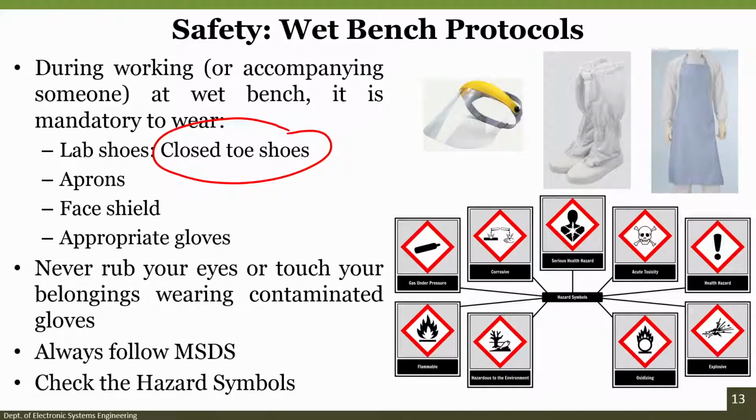So, you need to also follow the MSDS guidelines. You have to check the hazardous symbols when working in the clean room. As you can see here, there are a lot of symbols, for example, gas under pressure, corrosive, then serious health hazards. Even breathing these chemicals will cause a serious health hazard, like breathing VOCs, which are volatile organic compounds, will cause serious lung damage. Acute toxicity symbol is there, and oxidizing, explosive, hazardous to environment, flammable. You need to understand all these symbols, you need to take care while working in the clean room environment.